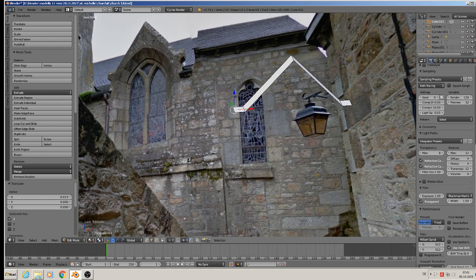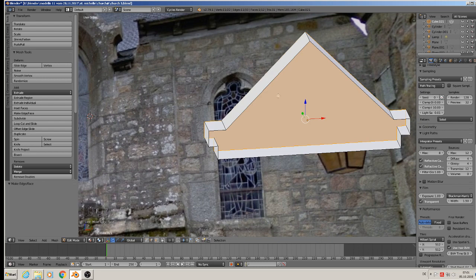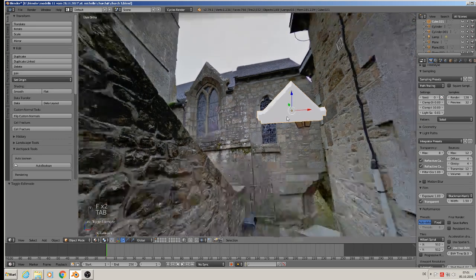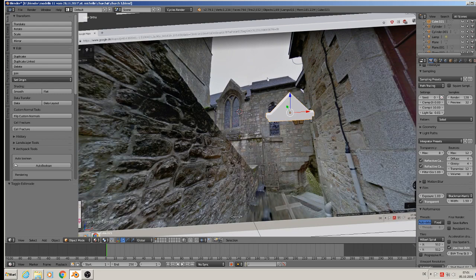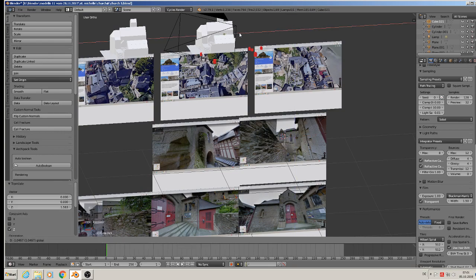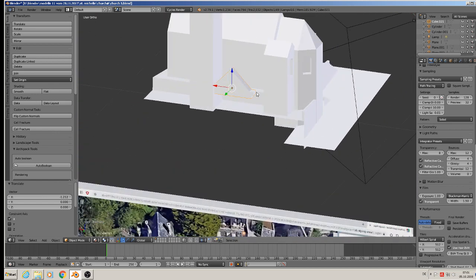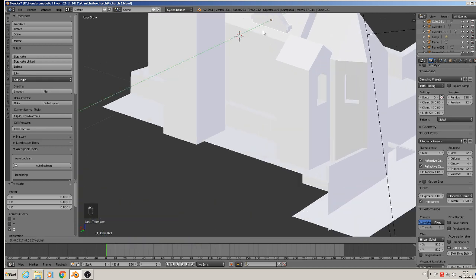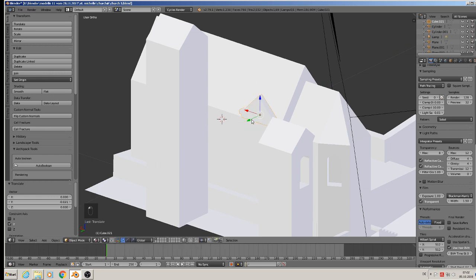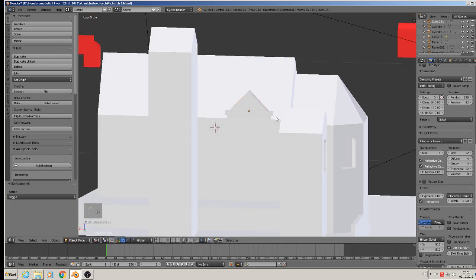Then that goes simply into the roof, so extrude, and extrude scale, so both come together here, and extrude downward. That is our base mesh, so F to close. F to close the back part and F for the front. So that is done. We plug that behind that roof there. So that means we bring that till that roof here. So that should be it.